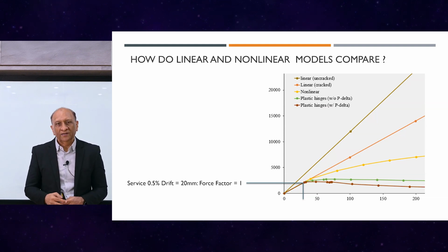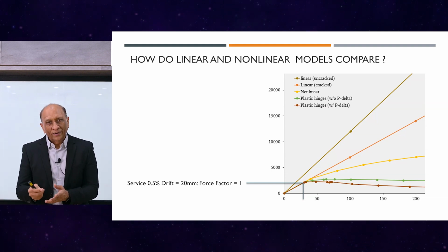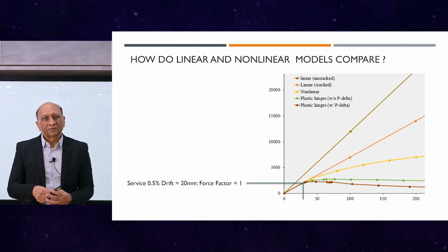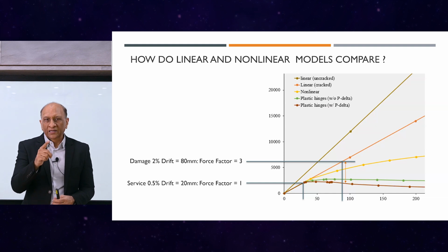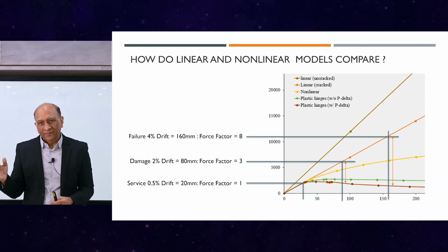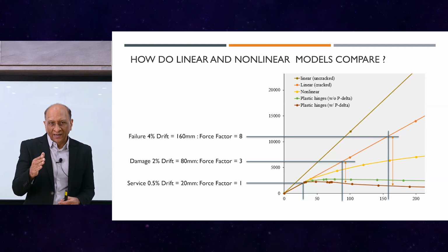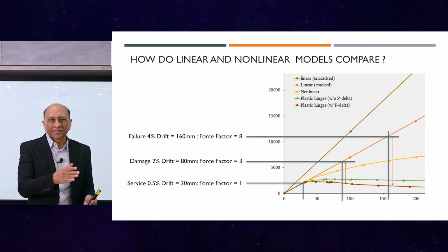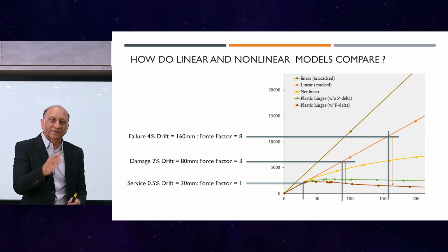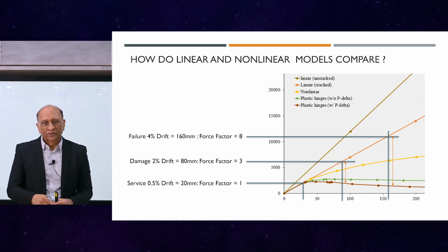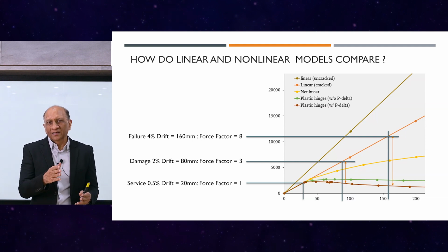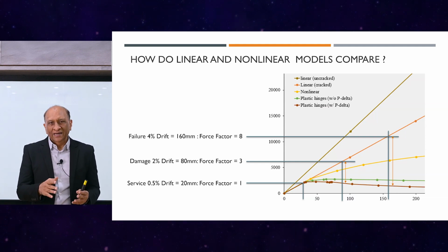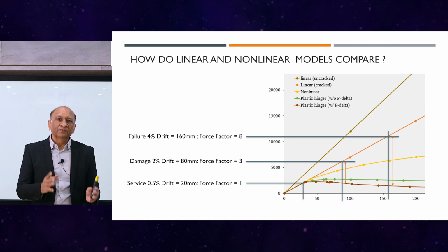As you can see from this graph here, this is a moment graph for various modes. The first mode, you can see the moment is pretty straightforward, and then you get the true demand, and from that, you get the elastic demand, and when you divide it by R, you will get the green one, and the red is the true demand, and somewhere in between, that's what we expect. A little bit more, so that's the omega factor between the green and the red. And that's what you will get for the first mode, which looks pretty good compared to the code.